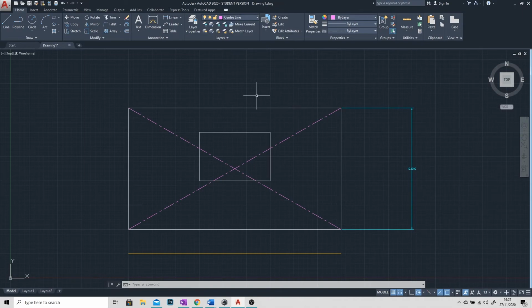One thing you may notice is that we changed the line weight for a couple of those layers. We changed it for elevations and ground plan. And there seems to be no line weight difference. And that's because by default, Autocad will hide the changes to the line weight just to make it a bit clearer and easier for you to draw.